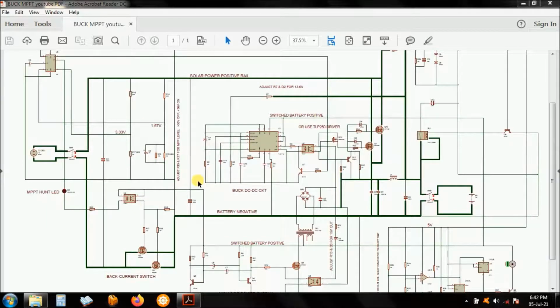That's an advantage. I've seen installations where people connect a 330, 350 or 400 watt solar module and charge a 12 volt battery. It appears like it's working for a few months, but later on you have a problem of the charge controller and even the battery getting damaged, because the system is not balanced. The best charge controller to use there is an MPPT charge controller.